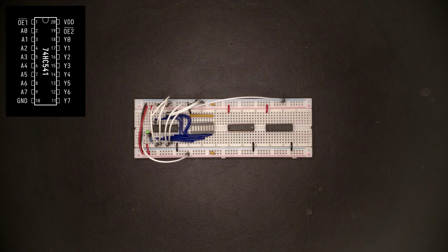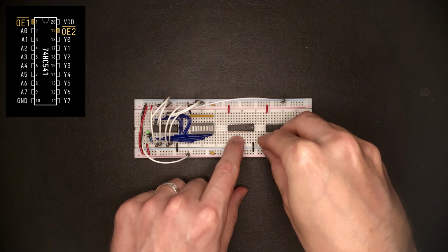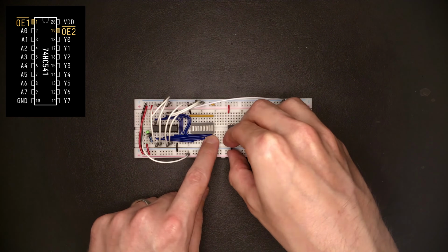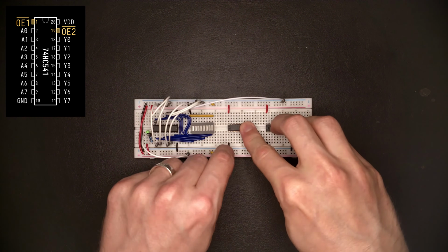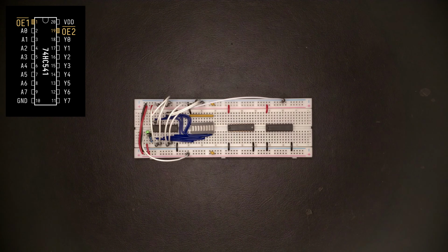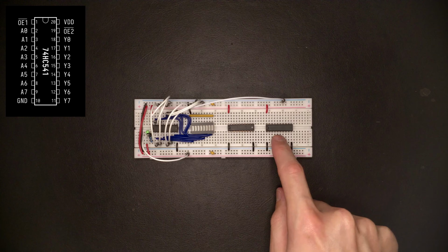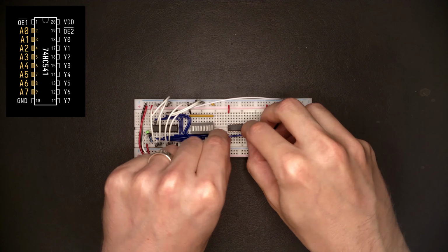And these buffers have 2 output enable inputs, and basically both have to be low for the output to be enabled and the chip to actually drive a value onto its output. But we only need one of those inputs to actually select a register to drive. So let me connect the other output enable input to ground such that it is constantly enabled. Now let me bring the 8 bits worth of data over from the LEDs to the inputs of the 2 buffer chips here.